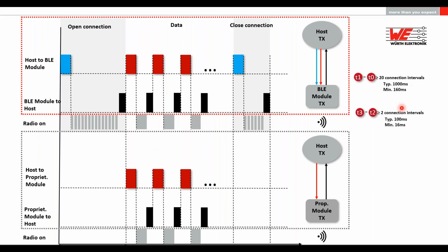So there is already an overhead of typically around 1,100 to 1,200 milliseconds before you can even start transmitting the data. This can be really critical. Let's say you are transmitting data packets of like 250 bytes, but you have to set up these connections, and in order to save energy, you have to switch off the radio module after disconnecting. So this is really the most important and deciding factor when you choose a wireless connectivity solution.